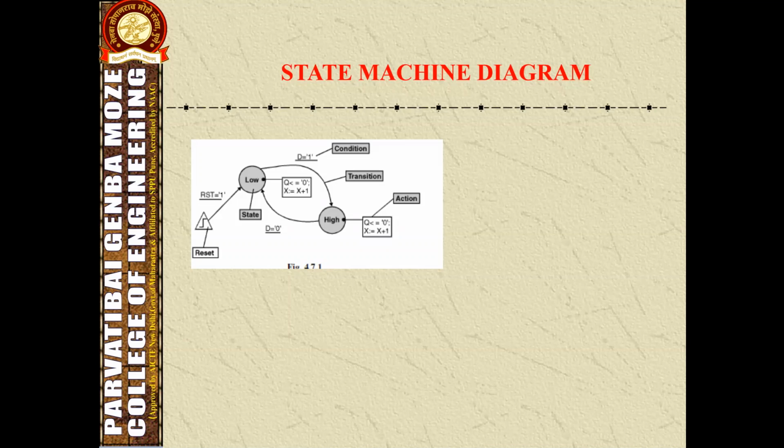Next one is the trap state. Here the designer declares a state to be the trap state. The machine transitions to the trap state on the nearest active clock edge. Further, the machine can be in a state different than S1, S2, S3, since the register signal acquires only three values: S1, S2, S3.